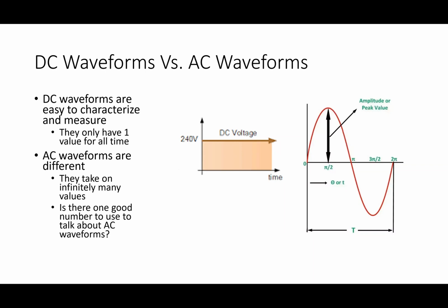Okay. So last time what I did was I introduced the concept at the beginning called RMS, root mean squared. Now, the reason we do this is because when we talk about a DC waveform, it's pretty obvious. There's only one number you can associate with it. Up until now, we've taken this waveform here and we've gotten rid of the fact that it depends on time, right? We've used phasors, right? So with phasors, we've used the amplitude and the phase shift. We're going to keep using phasors, except instead of using the amplitude, we're going to use the RMS value.